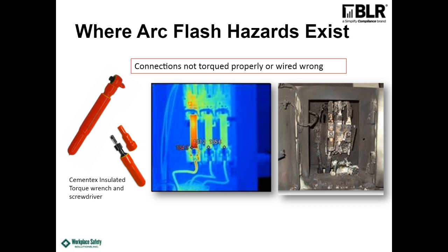And so they picked up this hotspot, and the hotspot, come to find out, was because the connections were over-torqued. And that happens a lot. So these torque wrenches and torque screwdrivers should be part of everybody's toolbox.